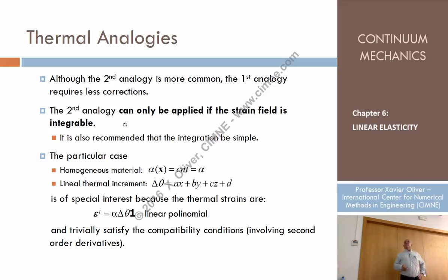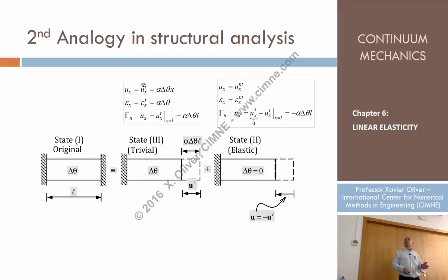So, first, the second analogy is the one that you know, is more intuitive. Let's decompose, release one support, make the structure statically defined, and then apply the thermal expansion, and then recover the boundary conditions so as to retrieve the original ones. Remember, that's structural, okay?